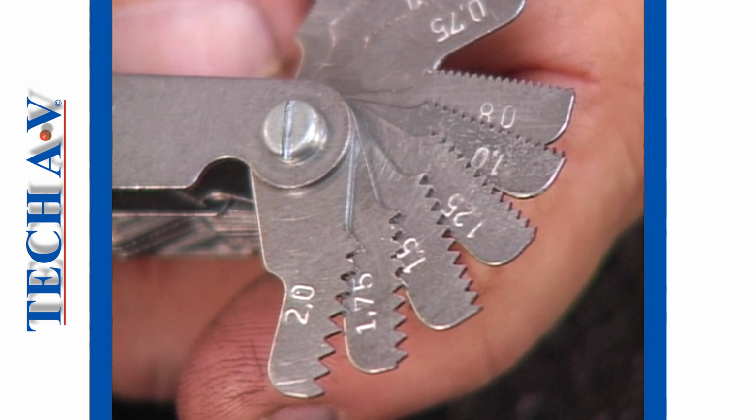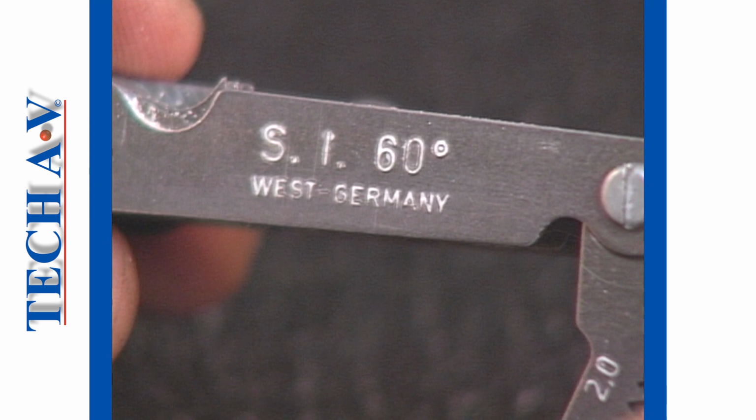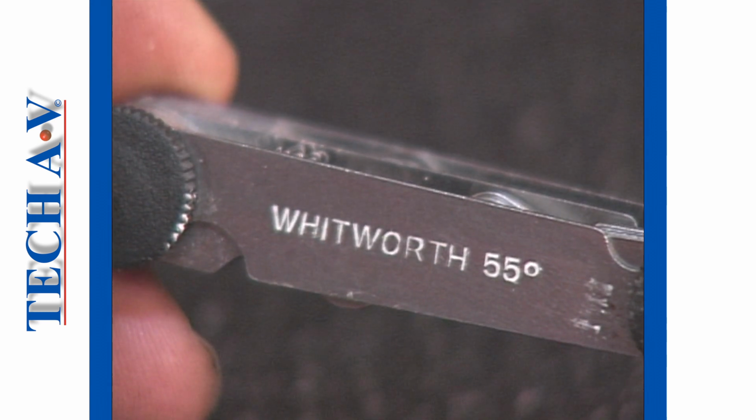Marked on each blade is the pitch in millimeters, on the example shown. The pitch gauge that we're going to use contains metric gauges in the side marked SI 60 degrees and Whitworth gauges on the opposite side. At this time, we will only concern ourselves with the metric gauges.